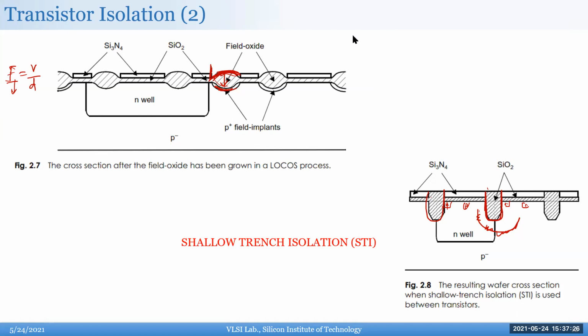Okay, so Sumiranjan is asking, the STI in the P well and N well will create a capacitance in between them. Yes, but it's a really thick trench isolation, which is still much better than having a resistor, right? Because your DC resistance is basically infinite, whereas you have finite DC resistance here. And with this shallow trench isolation, the capacitance is like attofarads, so it's pretty much negligible for most cases. You don't have to worry about that capacitance.